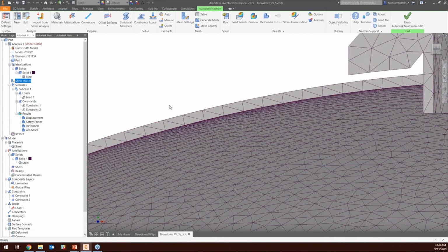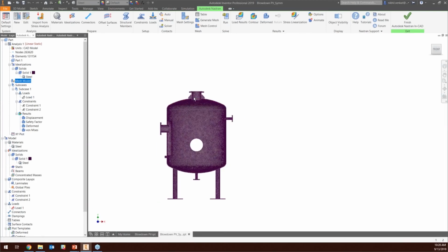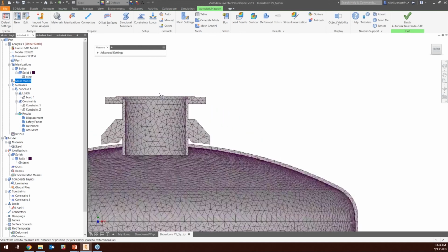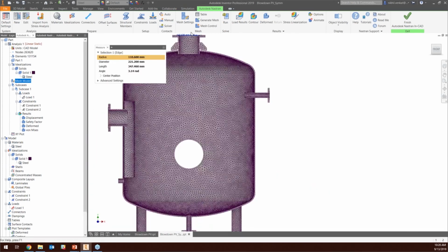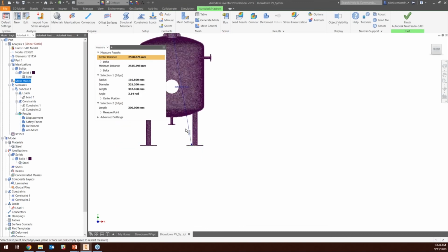When you're looking at solid structures, in regards to meshing, any areas of note is what I like to say in the particular model itself. Any areas where you're expecting something weird to happen, or you're expecting a very large difference between one side and the other side of a particular surface, you're going to want more elements, right?